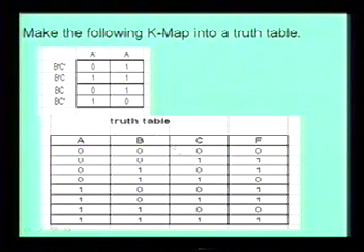And it's important that you understand this. We have not B not C, not B C, B C, B not C. You have to put it in this order for this to work. And that's kind of a hard thing to remember, because in your mind you're thinking that maybe it should be not B not C, not B C, B not C, B C, because that's kind of how binary counts, right? But you have to reverse the last two. So if you continue this, you'll actually build the entire logic.